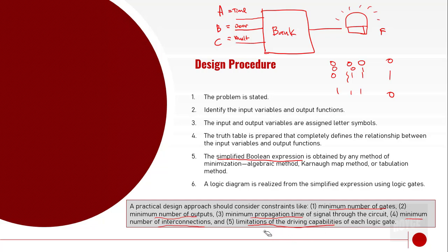Yung isang logic gate, hindi yan po pwedeng kukonek mo sa 100 logic gate. Take note, ang pinag-uusapan natin sa logic level is the output voltage, but there is also current in that. So, one logic gate cannot drive 100 or 1,000 logic gates connected to its output. There's only a minimum driving capability.